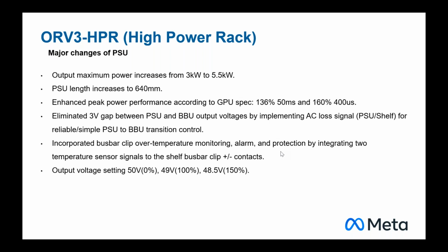But they are looking to support a 4-to-1 fixed ratio converter, and their target output voltage is 12 volt plus or minus 5%, including DC and ripple noise and AC transient. That's hard, because if you have an uncontrolled DC-DC converter, although you have a tight range on the bus bar, you still have a long distance from the bus bar to the point of the load.